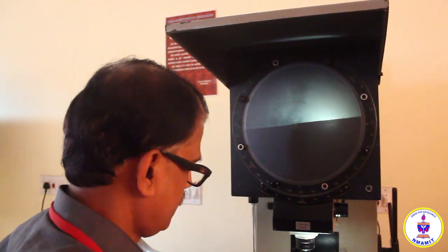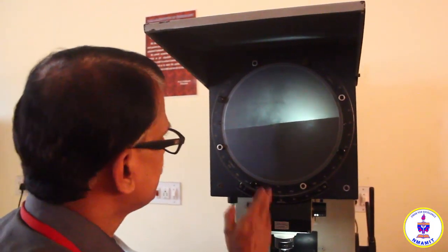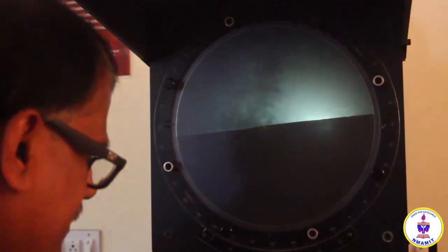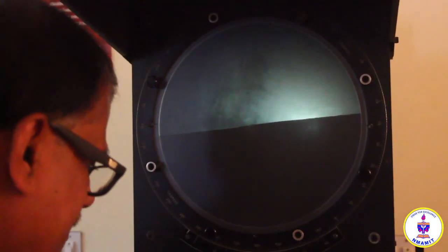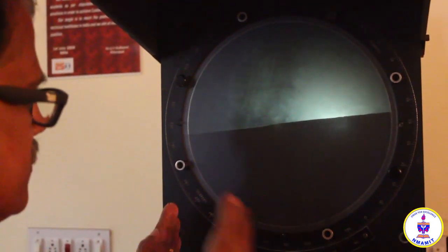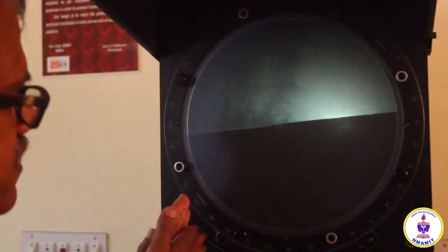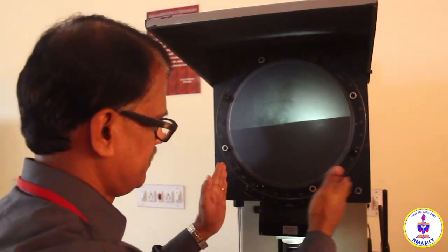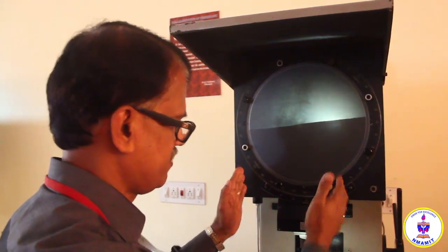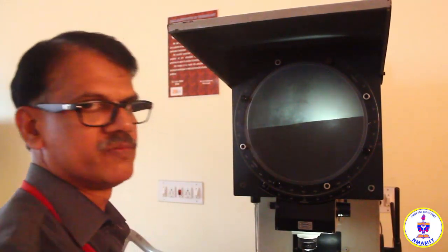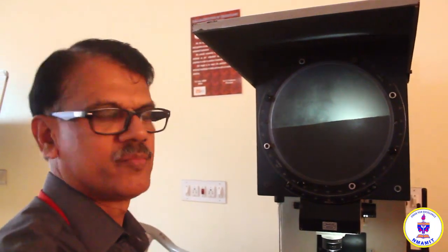Now here also, while positioning the image for taking readings, see that the readings are possible within the range of the micrometer. So after taking one diameter, when you move to the next section, the axial length must be chosen in such a way that the diameter there is within the range of the micrometer. That is the important point to be remembered.